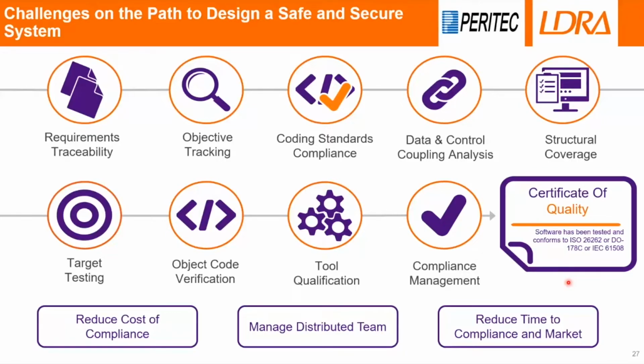The next activity is that while developing the product, you are following the safety standard and security standard. Every single objective in the life cycle activity needs to be tracked and you need to have evidence for it. For example, you are doing a requirement verification. You need to ensure that requirement verification is performed, and the evidence for it is a traceability report which shows 100% forward and backward coverage. So this is one of the evidences.